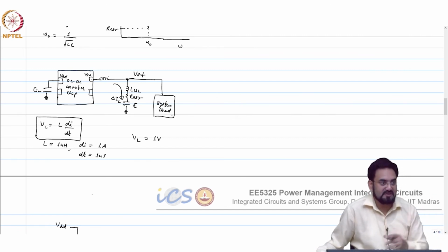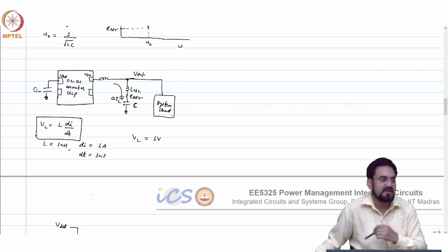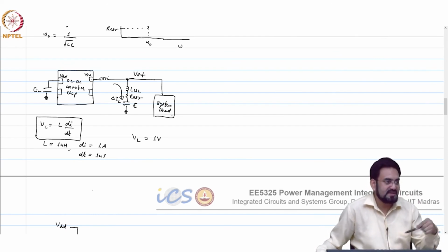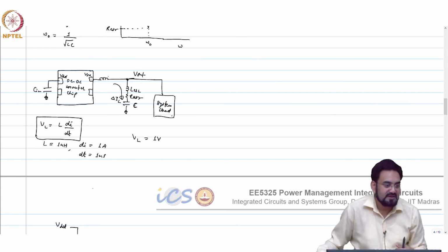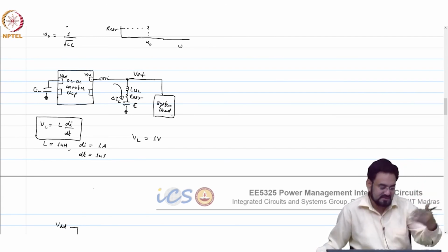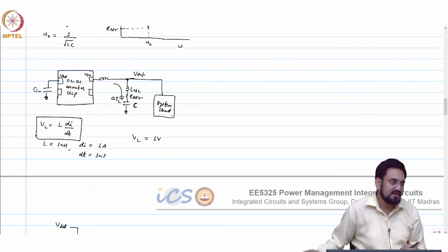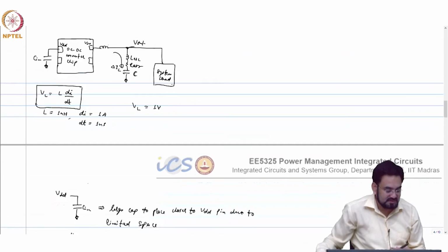When you are placing your FETs, you have to make sure that when you are routing those FETs and connecting to the ground, that should not have an inductance, because series inductance in that FET will be in series with the source of your bottom FET, and then at the source you will again see this L di by dt noise, and that may again damage that FET. So you have to care about that as well.